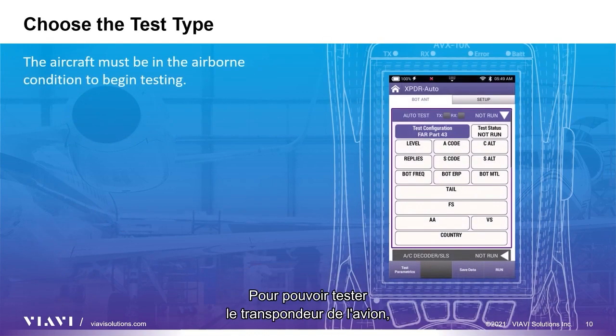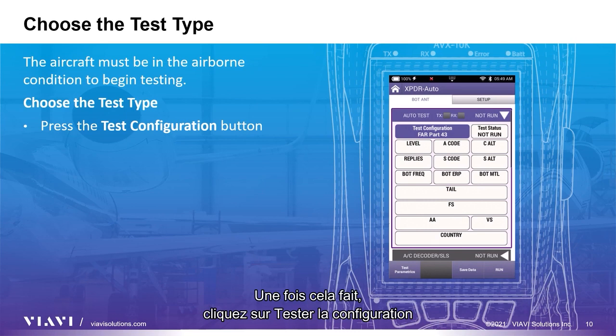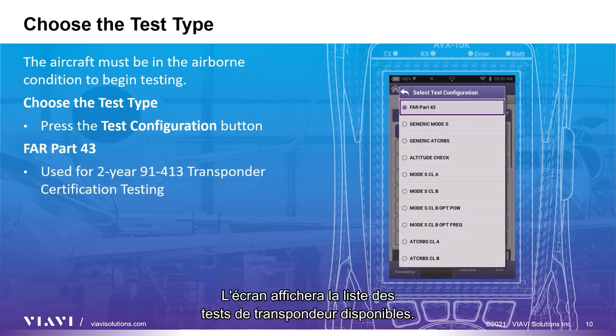For us to be able to test the aircraft's transponder, the aircraft must be set up in the airborne condition. Once that is done, press the Test Configuration button to select the transponder type to be tested. The screen will update with a list of all the transponder tests available.